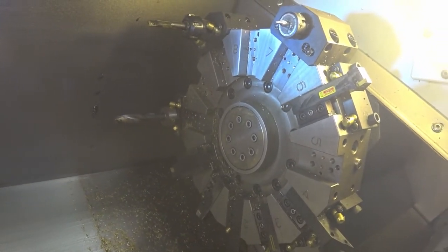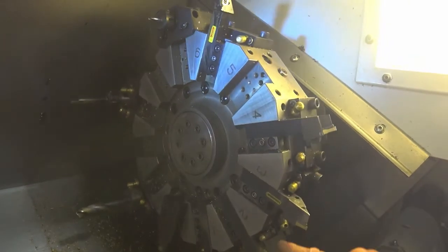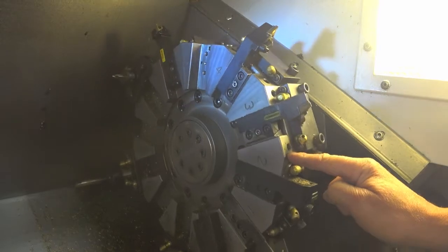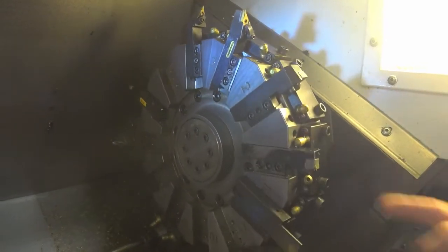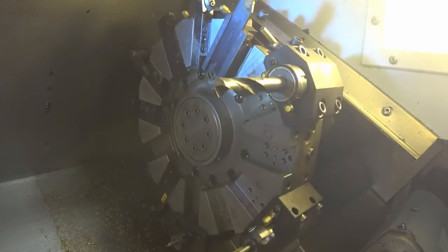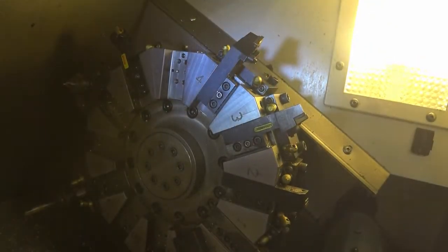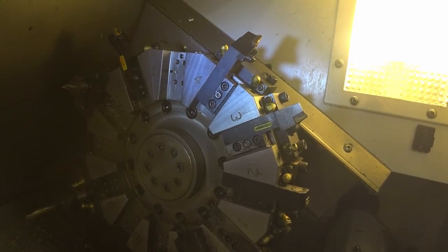Continuing to enter tool addresses and pressing the ATC key will result in the carousel rotating to the commanded tool location. Each tool address is clearly visible on the front face of the tool carousel. Note the large protruding tools on the face of the tool carousel, as they will require attention later on.